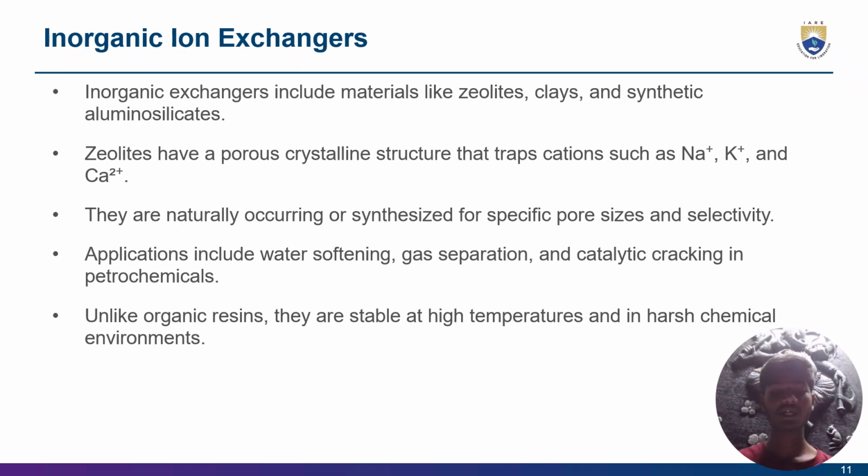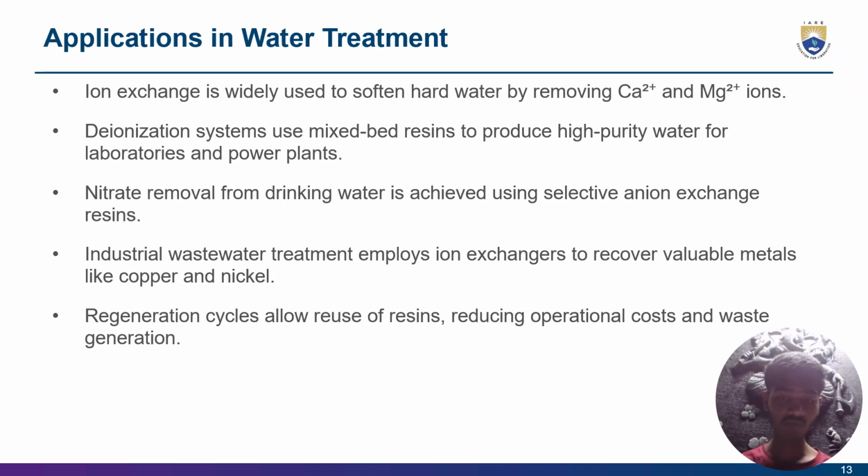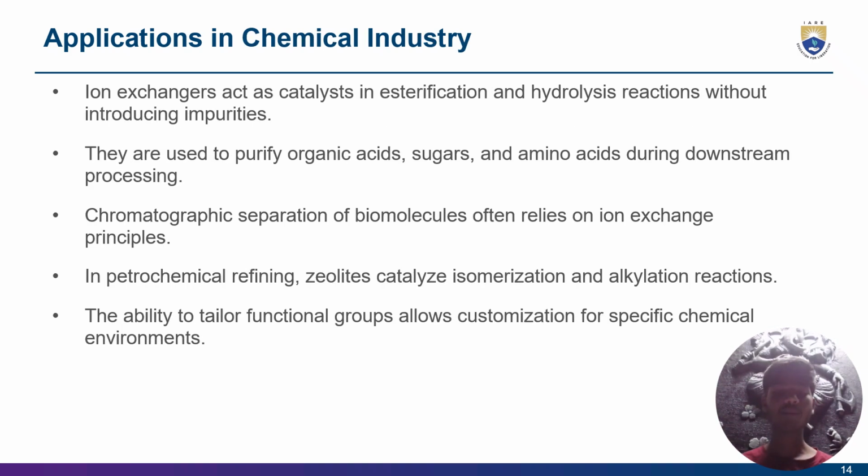Inorganic ion exchangers. Inorganic exchangers include materials like zeolites and clays. Synthetic zeolites have a porous crystalline structure that traps cations such as Na+, K+, and Ca2+. Organic versus inorganic exchangers. Applications in water treatment: ion exchangers are widely used in softening water and removing Ca2+ and Mg2+ ions. Applications in the chemical industry: ion exchangers act as catalysts in esterification and hydrolysis reactions without introducing